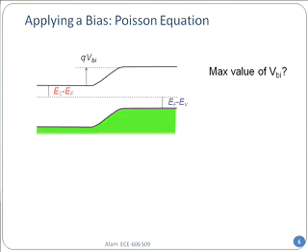Typically the maximum value you'll have is when E_C is getting closer to E_F, because you remember that in a degenerate semiconductor, it's very difficult to push E_F above E_C. So approximately, E_C minus E_F getting close to 0 is how close the Fermi level can be to the conduction band on one side. Similarly, on the other side, the Fermi level can approximately be equal to the valence band, a little bit more or a little bit less.